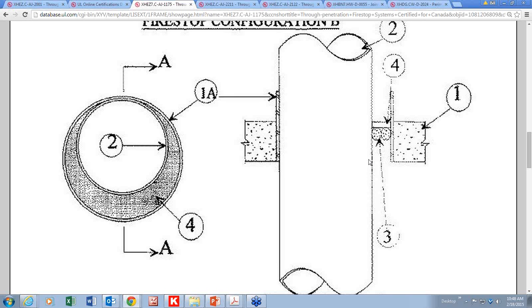we would recommend that a destructive test take place. Cut one open, or have the contractor cut it open if you don't want the liability of cutting it yourself. And that's perfectly okay, because that's the way most of the installations go. And then measure to make sure that the thickness of the sealant is as specified in the tested and listed system. How do you do that?